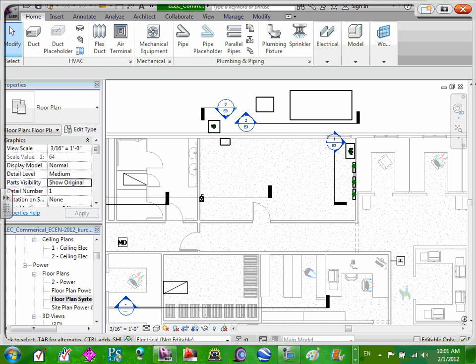Alright. So where the water comes into the building for the sprinkler system is basically in this corner of the mechanical room. There's a fire protection assembly for this building. It's where the water comes in, and it splits. Either it goes to the domestic water, to your faucets and your toilets and everything, or it goes to the sprinkler piping, which is for fire protection.